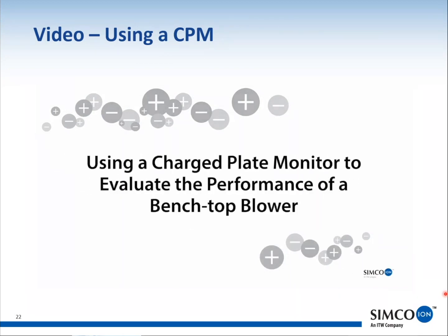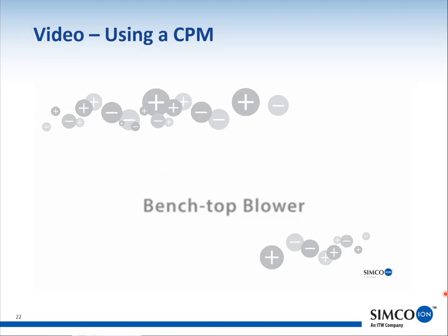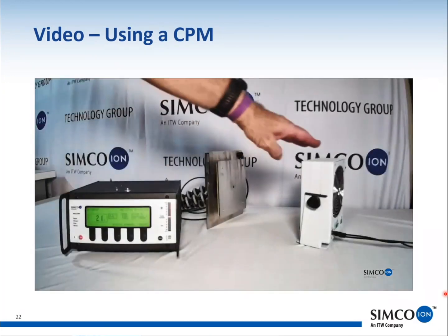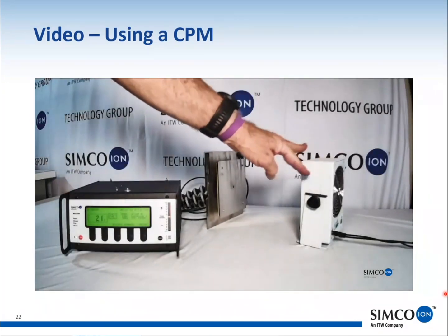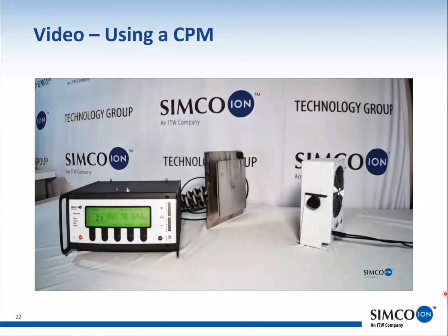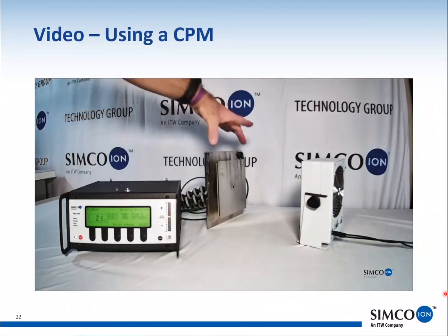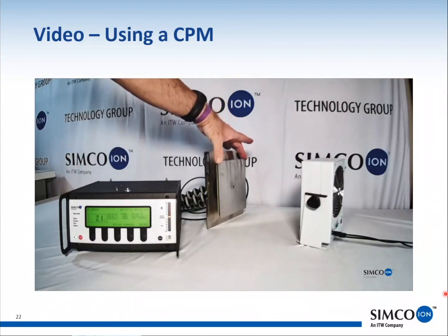Hello. Today I'm going to demonstrate how to use a charge plate monitor to do a simple measurement to evaluate the performance of a benchtop blower. Here we have our benchtop blower, and the airflow is coming out of it and hitting the charge plate monitor perpendicular. This 6x6 inch plate is the charge plate monitor.